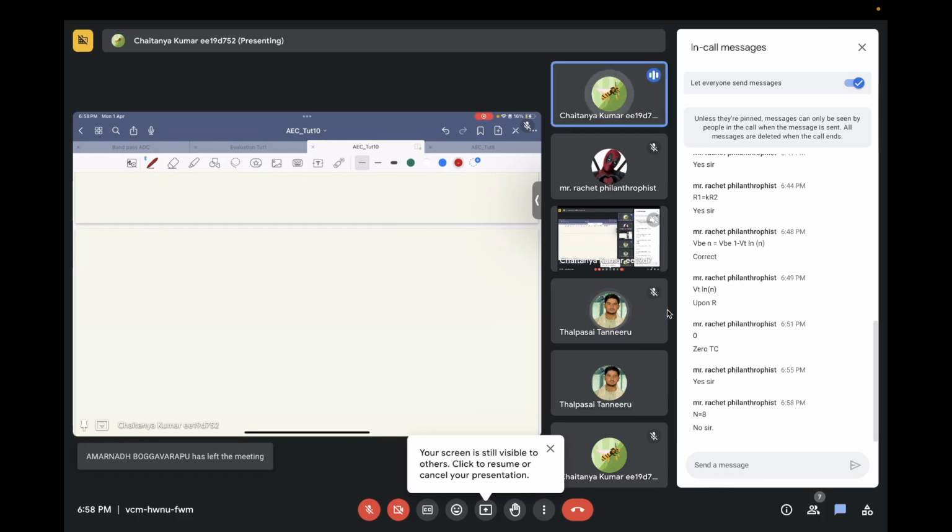So basically, the complete IC design process goes in this way. First of all, you get a PDK. What is PDK? PDK is a process design kit that will have information about the mobility of transistors, the threshold voltages of the transistors, the lambda of the transistors, and so on. Based on this PDK, you will use the model of the transistor to first design a circuit in schematic.